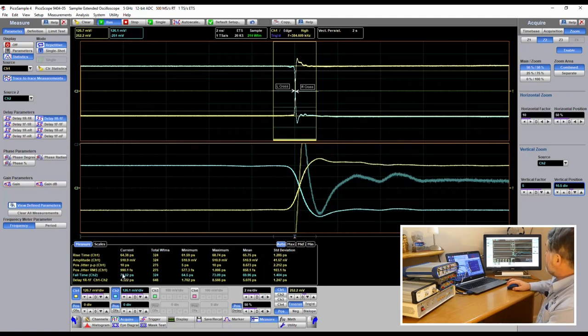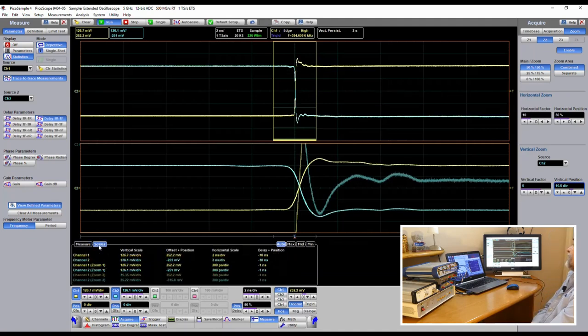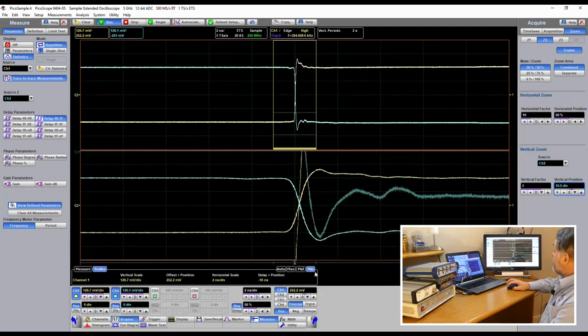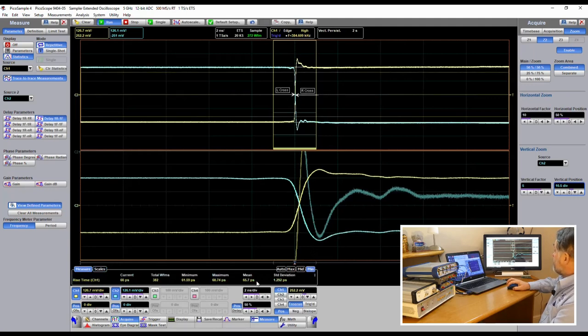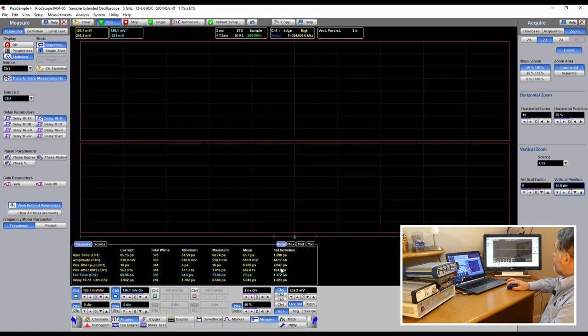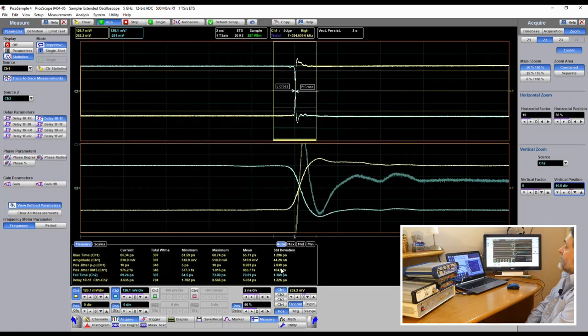If we look back here, we've got rather a lot of measurements up. We can move over and see the scales again. This is the scaling of all the channels and the 2 zooms that are currently up. We could choose to minimize that box, in which case that becomes a scrolling list for us. The same, of course, applies to measures. These are a scrolling list of measures, which we can rescale as we had before.